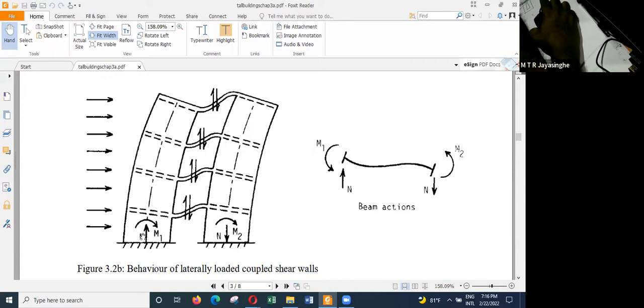And you can see these walls can be 3 meters, 4 meters long, and then you can have an opening of 2 meters, another 3-4 meters long. So you can get a lever arm of about 7 meters, and even for a small value of n, you get a huge reduction in the total bending moment.